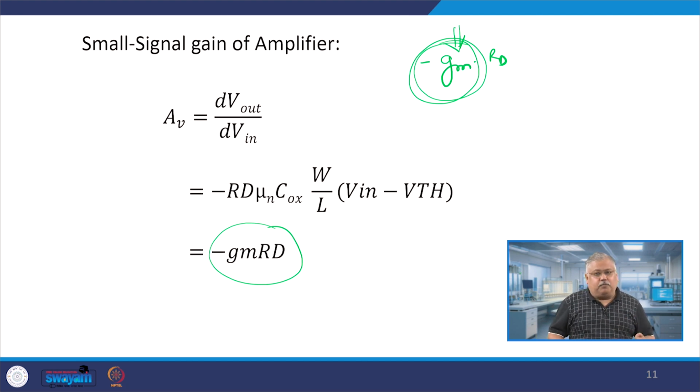And this is one of the major problems of designing an amplifier: I want my voltage gain to be independent of my input frequency, but that is not truly the case, as we have seen earlier. It is only constant between a set of frequencies. At very low frequencies the gain starts to fall with reducing frequency, and at high frequencies again the gain falls with increasing frequency. Where the gain is independent of frequency is the region we are looking into properly.